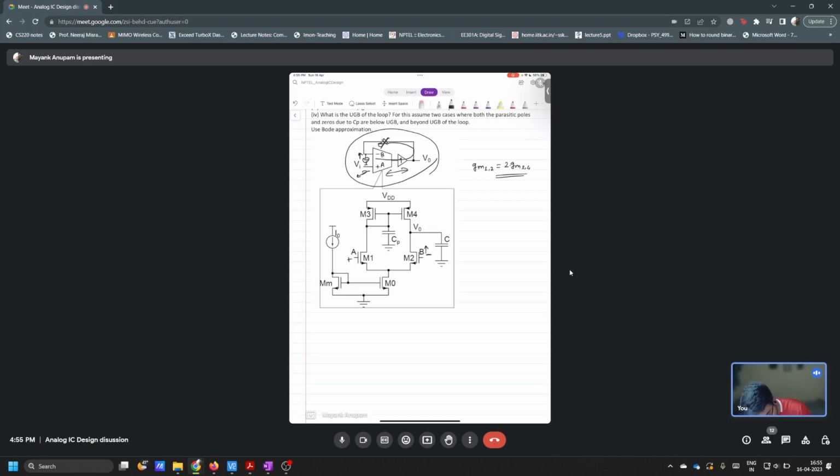So here, when you apply an input, this node will definitely decrease, isn't it? It is a common source, correct. It is not a common source per se. It is source degenerated, isn't it? Yes. So this will definitely go down, okay? And when this goes down, the output, basically the thing that is going to come here, is also going to decrease, isn't it? So that is why when you applied an input which is increasing, the return is decreasing. So now that means it is the correct sign, isn't it? Do you understand? Yes.